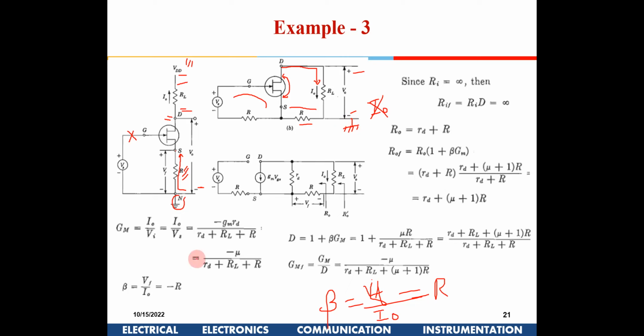Okay. Once this circuit is there, this is a pretty simple analysis, right? How to write an equation for them: this is V0, this current. Vs, this entire voltage will be available here. This R is not going to make any difference, because there is no current flowing here.